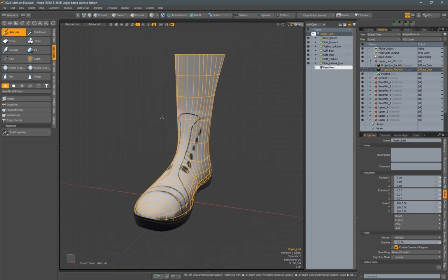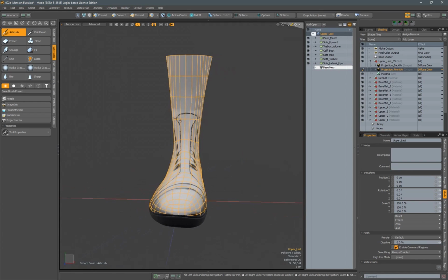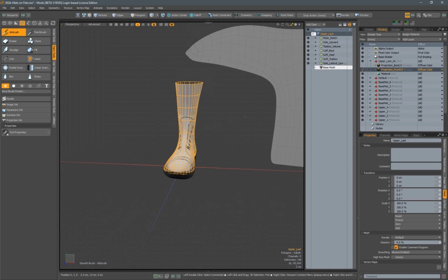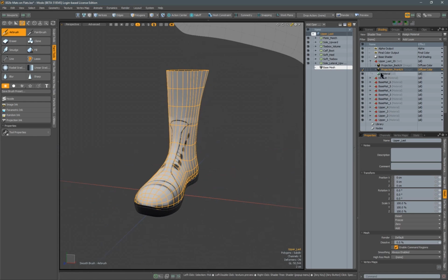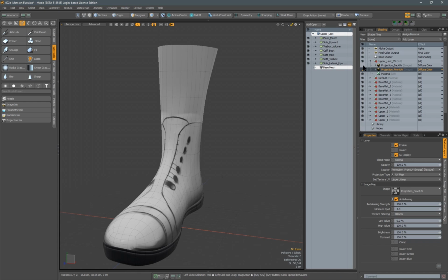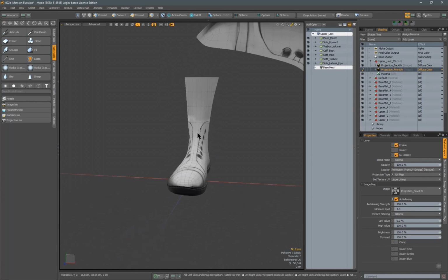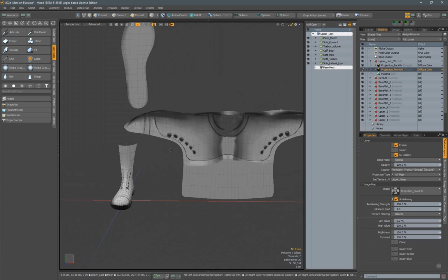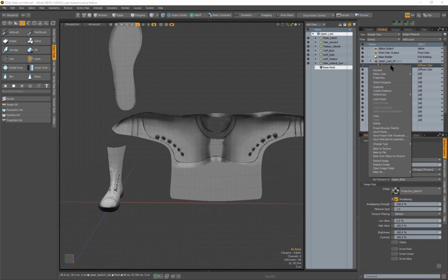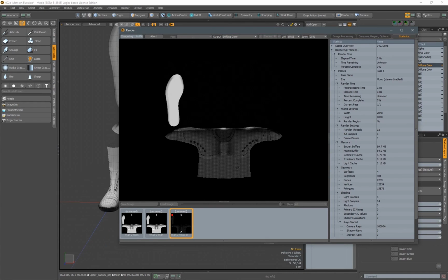Okay, that should do. And now we know where our tongue is going to be. And we still need to make sure that it goes across to the back UV. And if we activate that one, you can see it's no longer visible because we're turning on the back UV and it's overlaying that mesh right there. And what we need to do now is bake that to the back UV. So let's go ahead, right click on the back UV texture and then bake to texture.